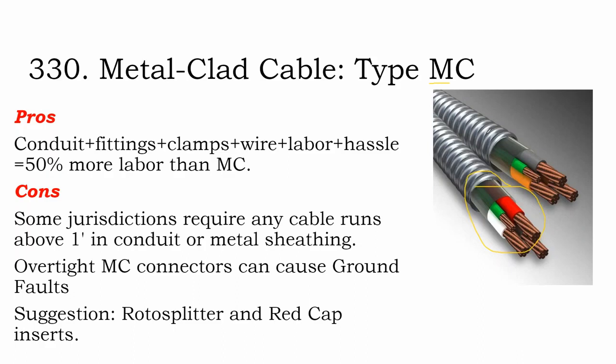And that really led to installers needing smaller than utility scale cable for home projects, for residential, small solar projects, but not having any product availability. And so the solution was, well, we'll run our metal conduit and pull single conductor cable through it.